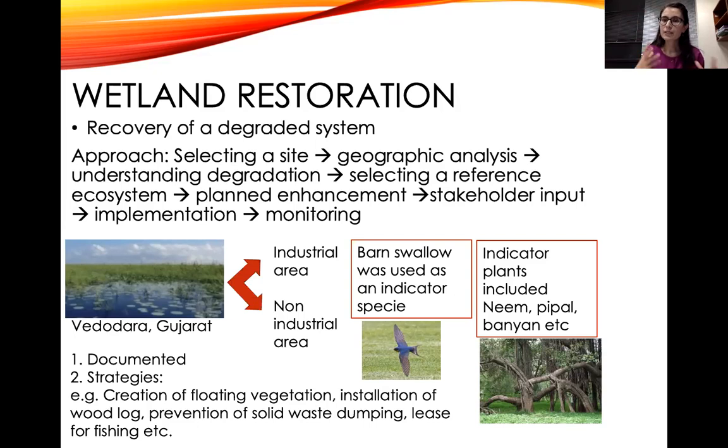But whatever method you're using depends on what you choose and what the contamination is, and how difficult that is. If it's an aquifer, if you've contaminated here, and then that aquifer just moves, you will have to trace the pollutant and treat it a few miles away from the city, downstream somewhere, and that depends on the flow of groundwater, right? That means that you will treat this particular part of soil separately, monitor that groundwater pollutant, and extract it at a certain other point, specifically if you're extracting groundwater for drinking.